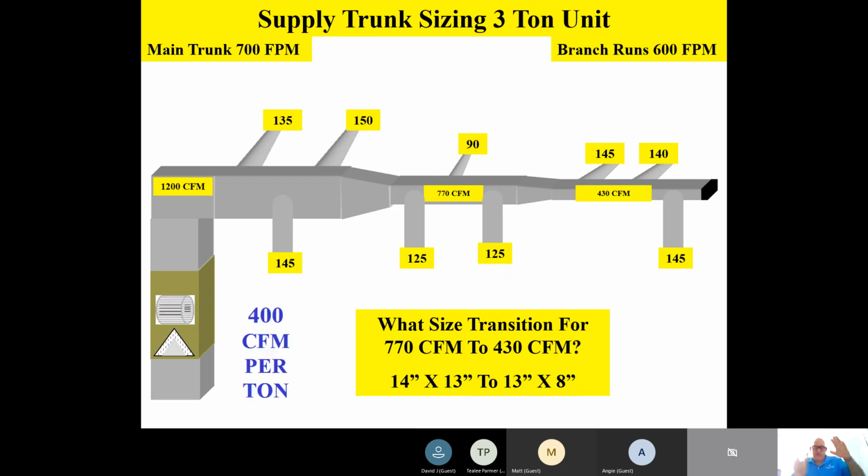So if I take 4,800 cubic feet of air that's going to be exchanged per hour and divide it by 60 minutes in an hour, how many times does 60 go into 4,800? 8 times, right? 80 times to be specific. I'm just dropping some zeros in my little third brain cell. So that'd be 80 CFM in that example.